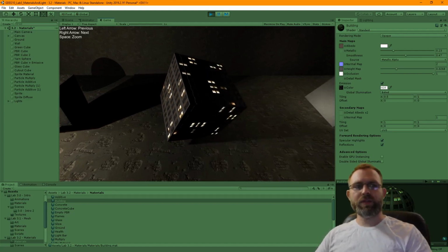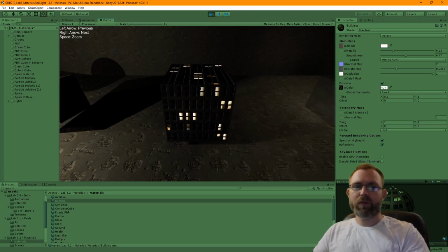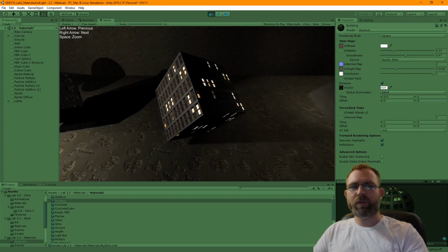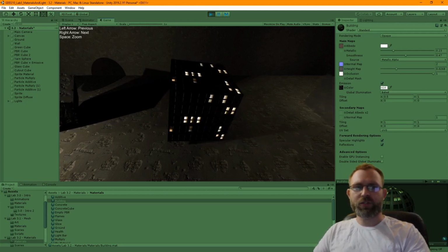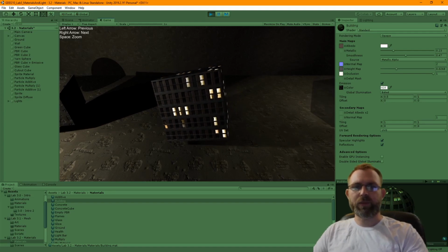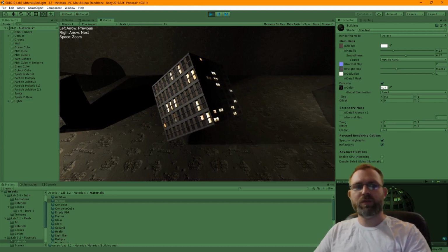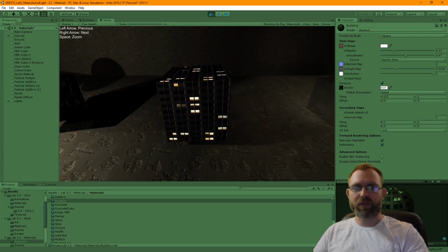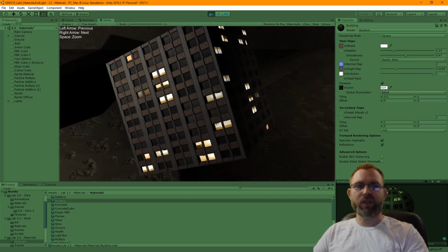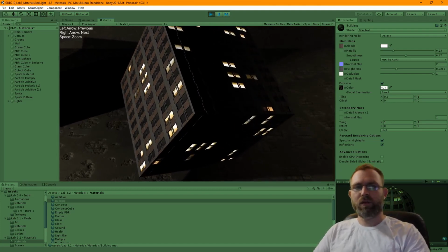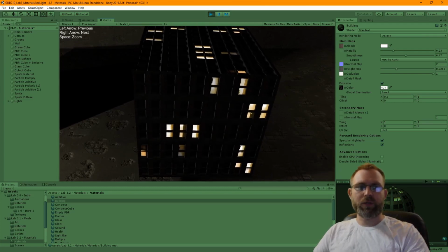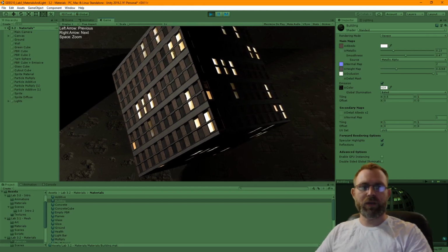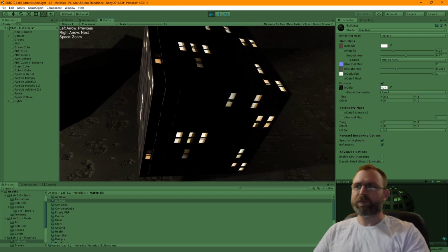The next cube in our scene has the building material applied to it. Like our other PBR materials, this has an albedo, normal, ambient occlusion, and height map to give it loads of detail. It also has something called an emissive map. This is another texture we can use to control the look of our material. An emissive map refers to a texture which tells the material where it should emit light from on the surface of the object. In our building example, you can see that the windows stay bright even when the faces of the mesh are in the dark. This is great for things like windows, computer screens, glowing buttons, etc. They allow part of our texture to appear illuminated and can contribute to the light in a scene.